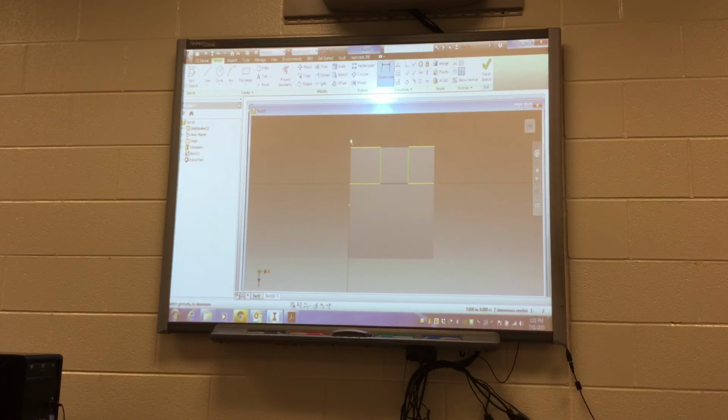So now I have to dimension it. This one right here is where most students mess up dimensioning. A lot of them will just say that's done right there. Is that done? No, because I haven't chosen any side. Right now we have to dimension in a little bit different way than what we've done before. I have to add a dimension to show how far apart these two lines are. To do that, I can't just click on this line right here because it's making me select the whole thing. So you might have to click on what two lines will my dimension be between, and then click one more line to place it, and then make it a 1/2 inch.